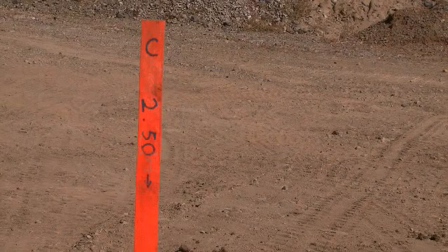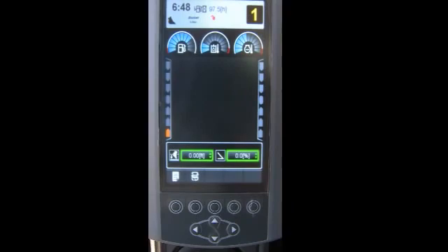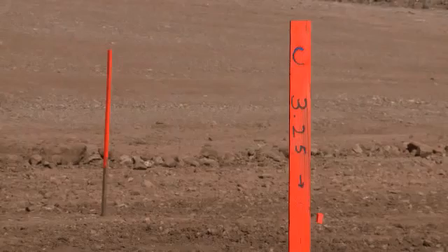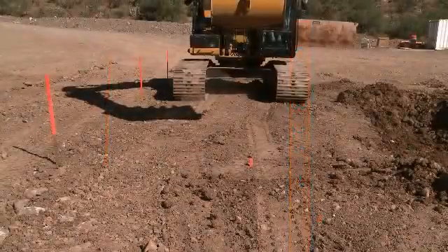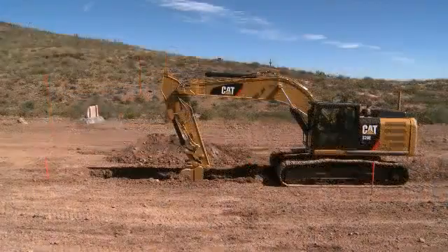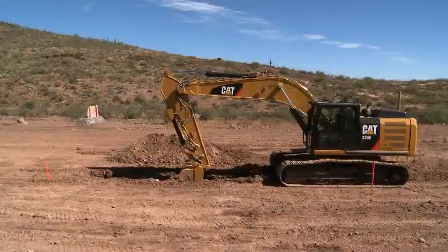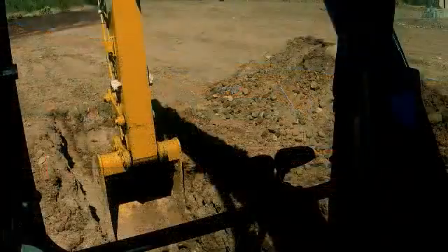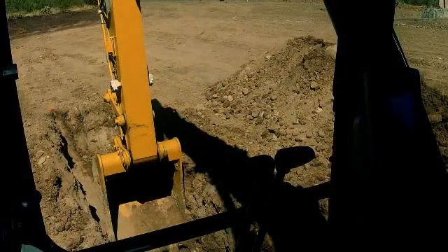The same uses of reference elevations and entering offsets apply. For a sloping trench, be careful to read the offset value for each grade stake, as they may change value for each reference. To use the touch point feature for a sloping trench, use a point in the bottom of the trench near the undercarriage.